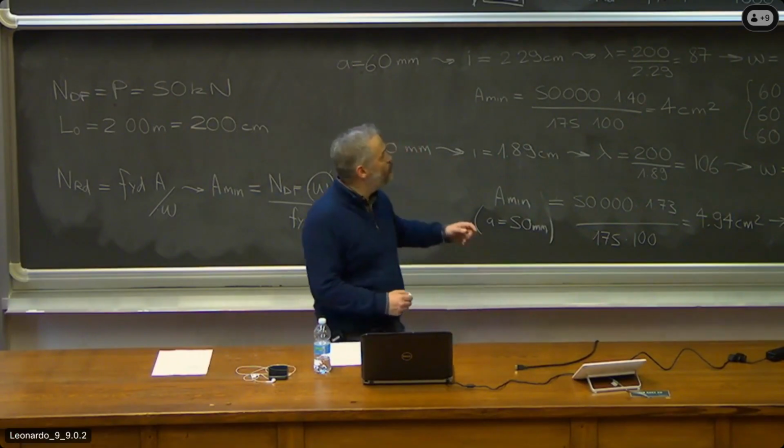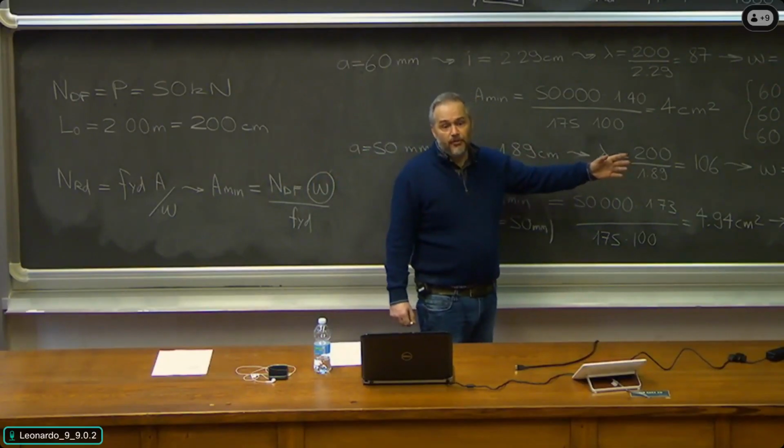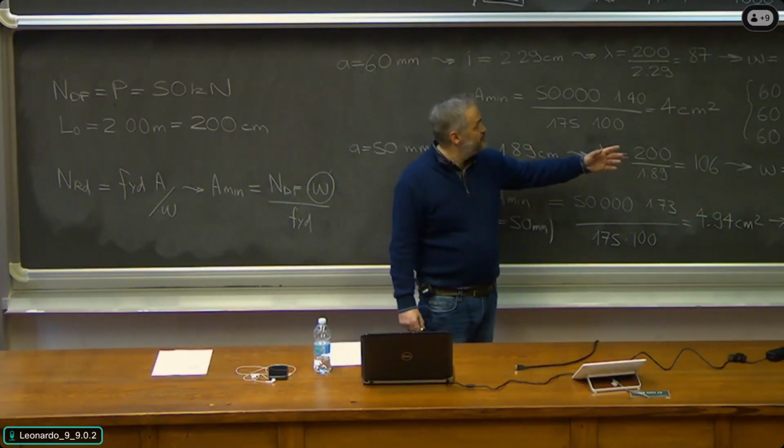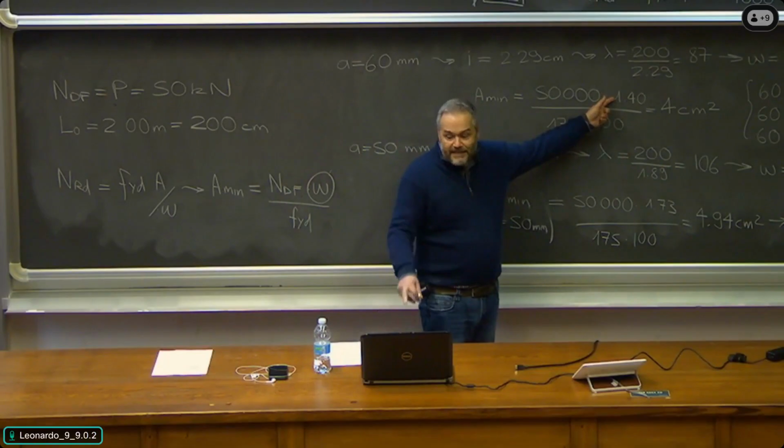I think that from what we did, you could grasp the problem with the design of compression members. When we have to specify omega, we have to make an assumption. In this case of the square hollow sections, working group-wise on the basis of width and depth, so the first number in the table, is an effective way to go. Okay?